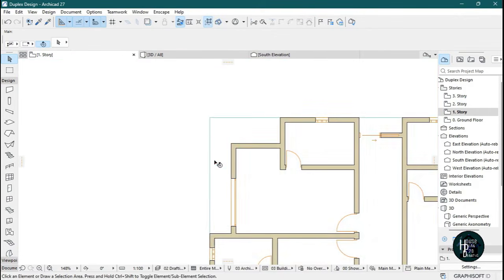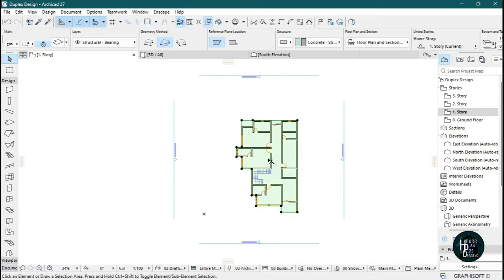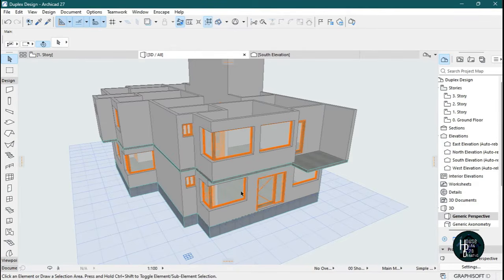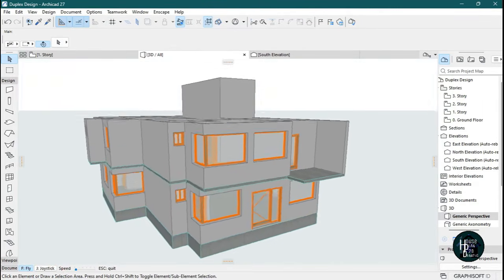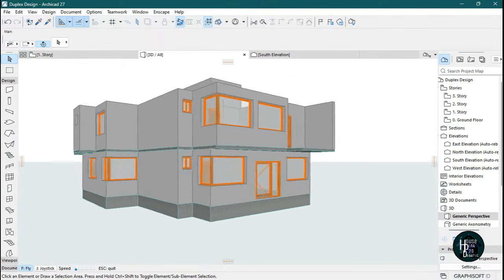Okay, for this other side I also want to just cut out this part, like this side off. So I'm just going to click on the node here and try to stretch it to the side, so we have something like this. If you go to your 3D view, you should be seeing the slab perfectly shaped with the first story building, as you can see.